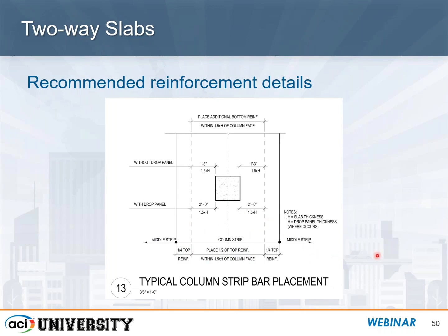The other way I've seen it done is actually having the column there and those bars actually shown on that particular detail of what the concentration has to be over there. Whichever you prefer to use is up to you, but in these cases, this is an often forgotten detail that can cause some serious consequences if it's not shown properly on the drawings.